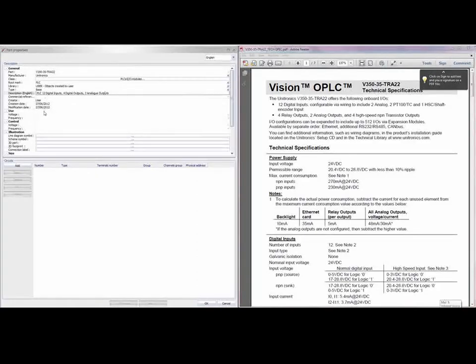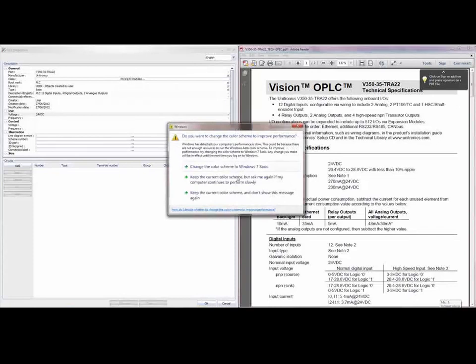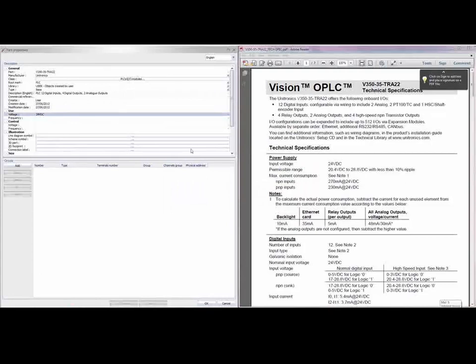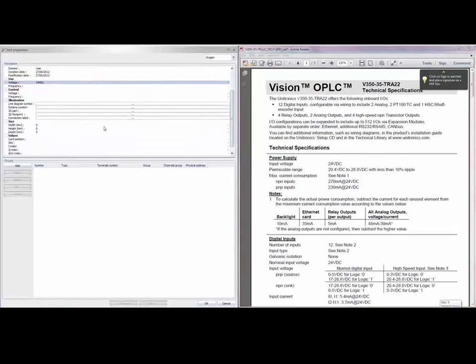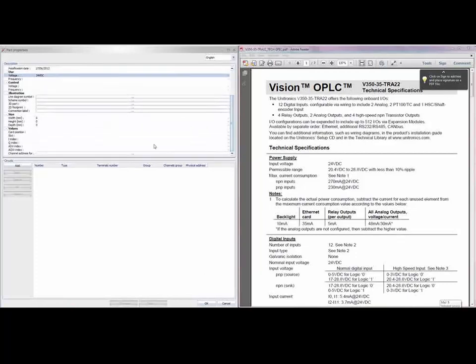Of course it may have a different reference there, and I'm assuming it's 24 volts DC, 24 VDC, and we can even specify, can obviously specify the sizing information, etc. So it will generate a 3D model just from basic height, width, depth information. You can also define the address system, etc., and the card position if it was a card based system, but this isn't, so we don't need to fill any of that in.